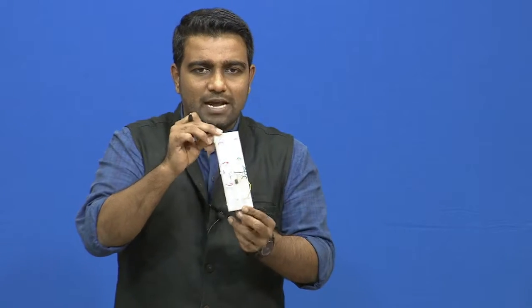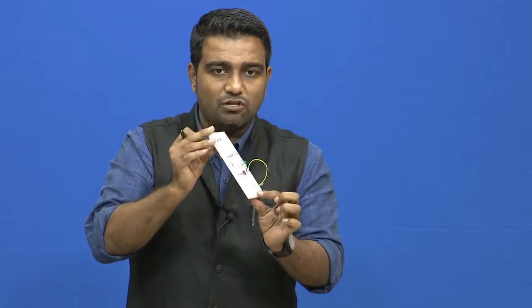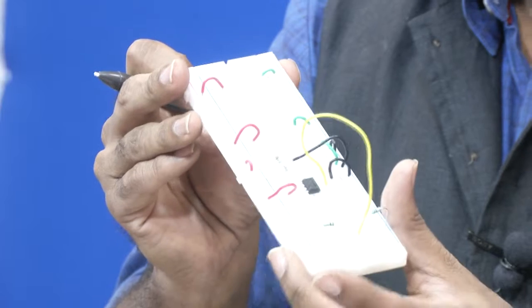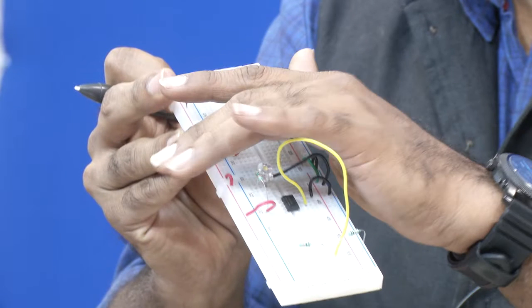That is what we do with CMRR, right. That is why we require high CMRR, common mode rejection ratio. We increase the signal, we reduce the noise. In the same way, if you want to reduce the noise, this is just a crude example, do not take it as an actual example. I was just showing you that if I have the LED as a signal and the remaining things in your image as noise, how can I remove the noise and consider only the signal, alright.